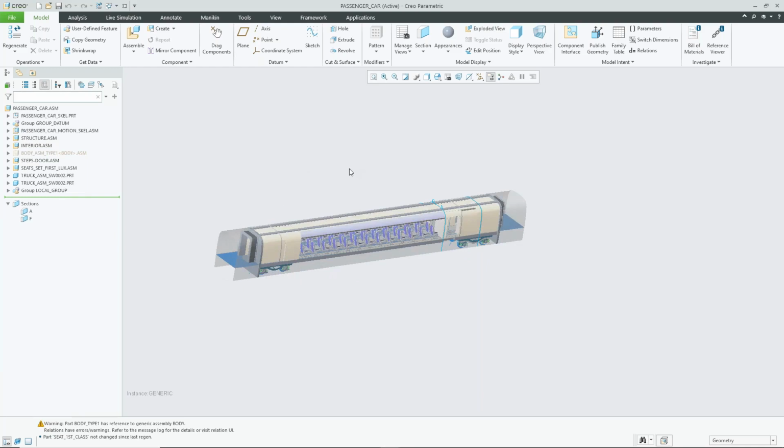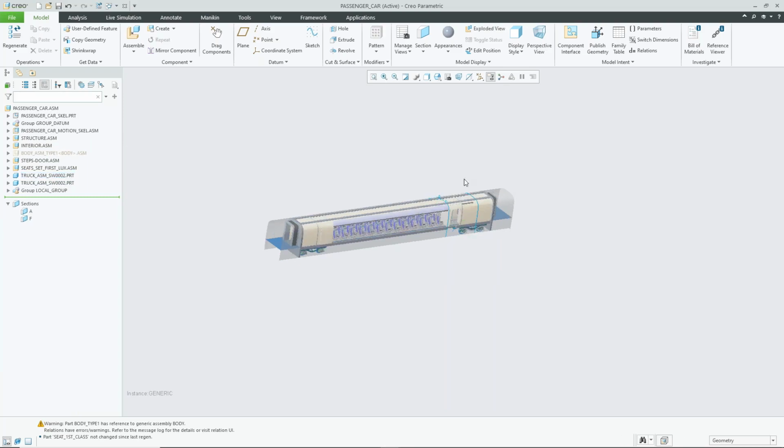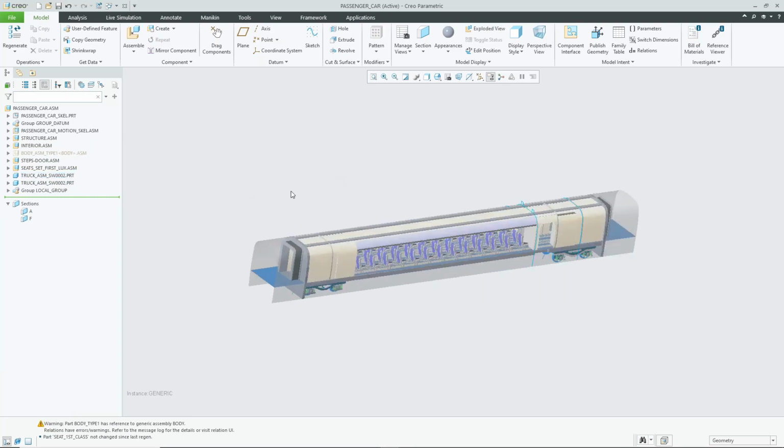That's once again, when we look at where all the engine components are, remember, they have that entire engine listed as a single part because it's simply a shrink wrap. And that's what we have here. So this entire assembly is actually a single part file of surfaces. So that makes it a lot quicker and a lot easier to go through and regenerate your assemblies.